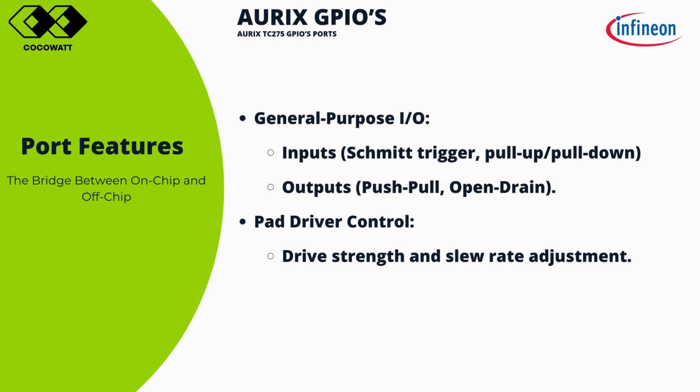On the output side, you will find push-pull mode. This can drive the pin high or low, making it ideal for controlling an LED or motor. Open drain mode only drives the signal low and requires an external pull-up resistor. It is commonly used in I2C communication.